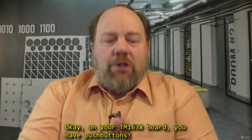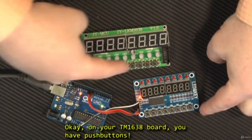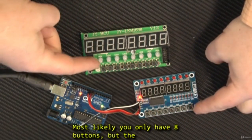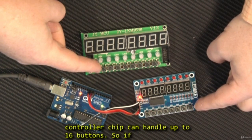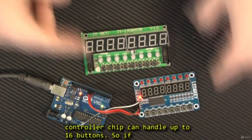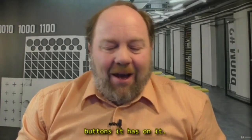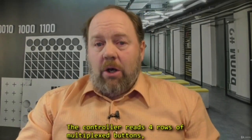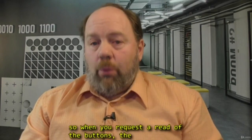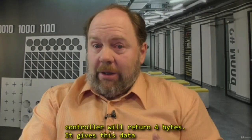Okay, on your TM1638 board, you have push buttons. Most likely you only have 8 push buttons, but the controller chip can handle up to 16 buttons. So if you supplied your own board, who knows how many buttons it has on it. The controller reads 4 rows of multiplexed buttons, so when you request a read of the buttons, the controller will return 4 bytes.